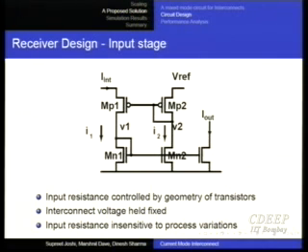Okay? Current comparators unfortunately have a moment of indecision if the two currents are exactly equal. So that makes this circuit a little slow, which enabled Marshall to throw out this wonderful idea. However, this circuit works quite well, and if you can afford to have a delta I which is rather large, then this is a very effective circuit.